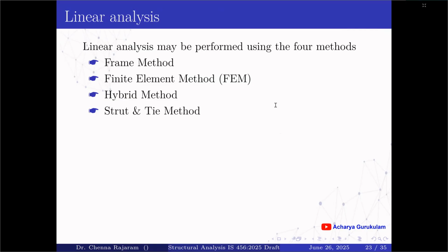The strut and tie method shall be considered when the structure consists of complex load paths, non-uniform stress distribution in non-prismatic members, and junctions of members of concrete structures. This method is meant to perform local analysis and shall not be used as a substitute for the overall global structural analysis of the structure.